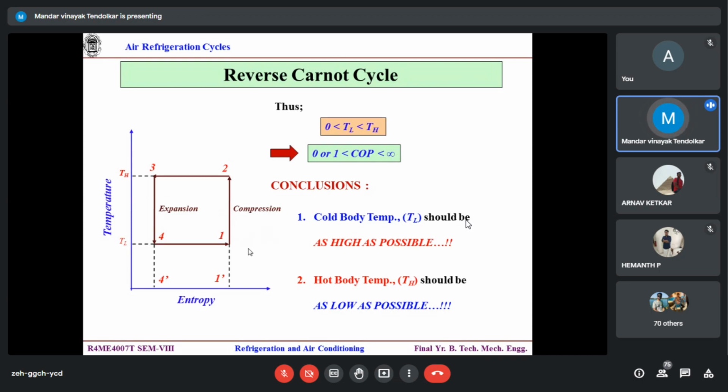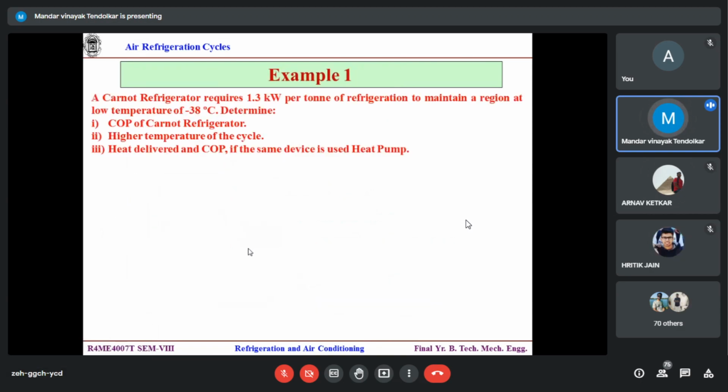Practically, you cannot use the same motor to run the compressor and to reject the heat. To reject the heat in the piston cylinder element, you have to move the piston very, very slowly. But to compress the air inside the piston cylinder element adiabatically, you have to move the piston with infinite speed. Do you agree? Yes, sir. So it is practically impossible. Correct? That is the reason.